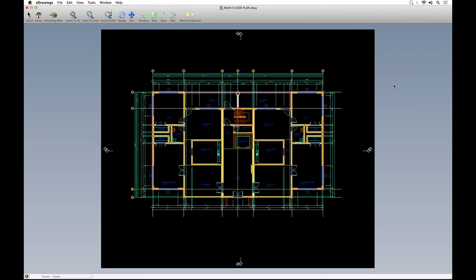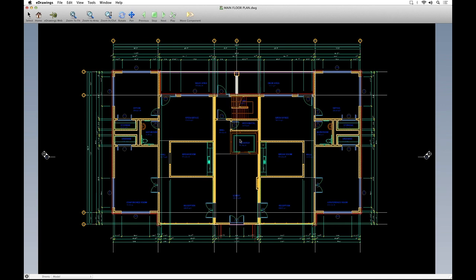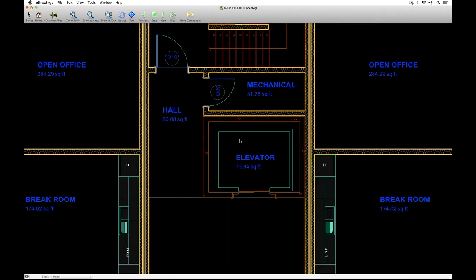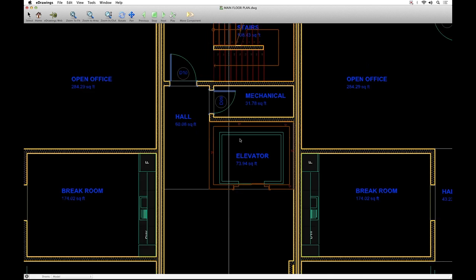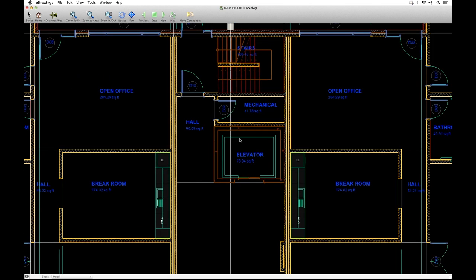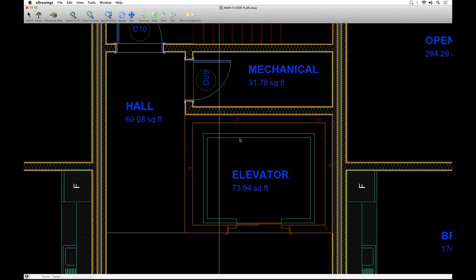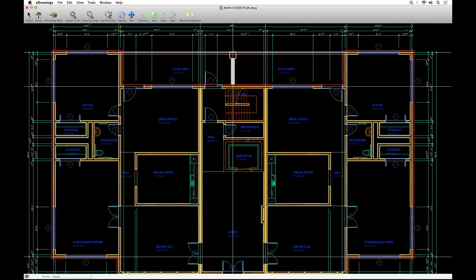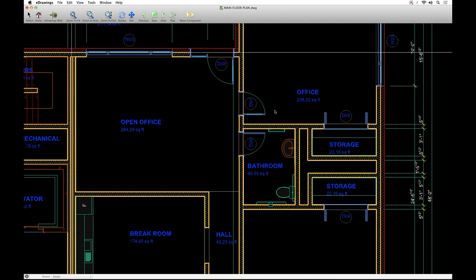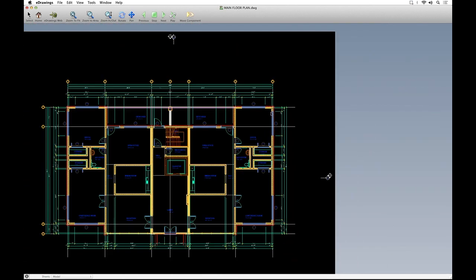Next, we'd like to show you, we imagine almost everyone has to export one of those flat old 2D DWG files at some point in their project. Have it as part of your publisher set. You can set up your translators specific to a specific consultant or engineer. We strongly advocate getting your entire team using ArchiCAD, be it structural, mechanical, electrical, interiors, all your consultants. But if they are using DWG, let's make our lives easier. Find out how they want their work, how they like their layers, whatever. So use that translator, set up the DWG as part of a publisher set and export it.